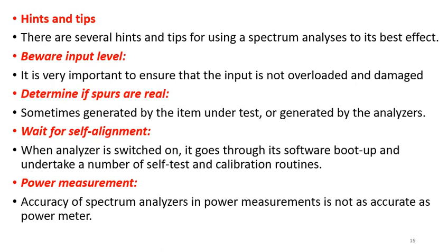The next thing is you have to wait for the self-alignment. That is, when you switch on the spectrum analyzer, just like your computer system, it will boot. After booting, it will calibrate some parts of itself in order to take accurate measurements. Finally, for power measurement in the spectrum analyzer, we should know that the accuracy is much lower compared to an ordinary power meter that could be used easily.